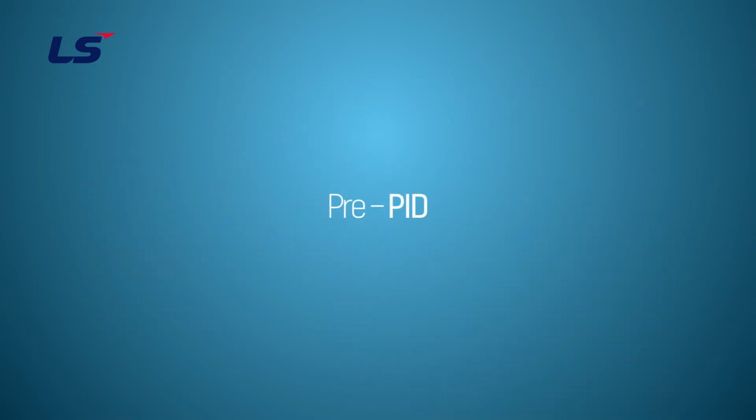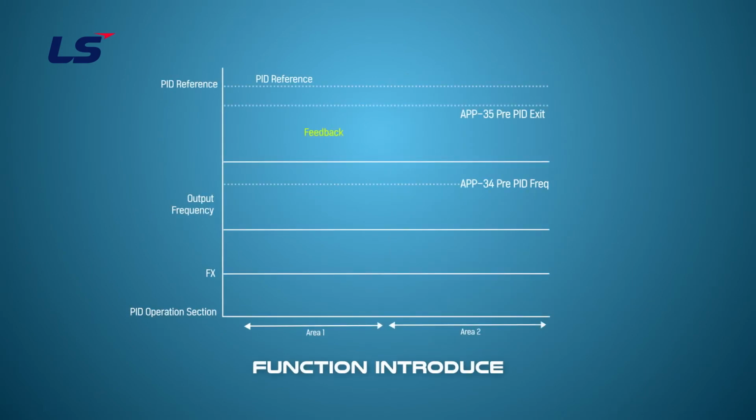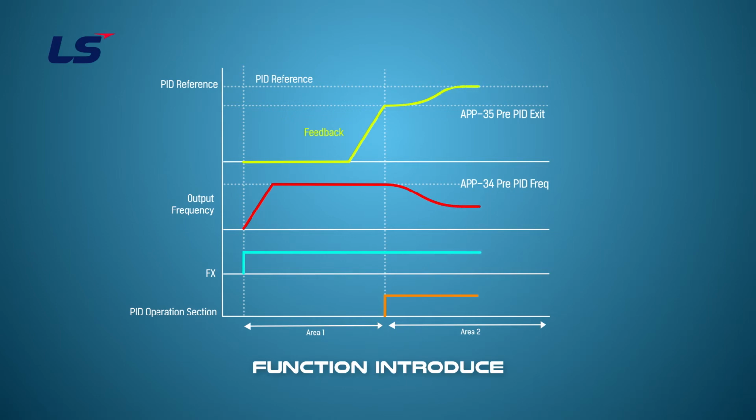Next, let's look at the pre-PID function that can operate at a constant speed without PID control, only when the feedback value is low at the beginning of a startup. Pre-PID function is a function that performs normal acceleration without PID operation up to the set frequency when an operation command is entered, and starts PID operation when the feedback value increases to a certain level.